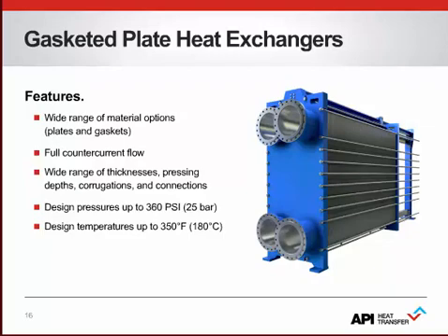Gaskets are typically made of rubber, such as nitrile or EPDM. Also, some fiber gaskets are available. The gasket is the biggest limitation in gasketed plate heat exchangers, both in terms of pressure and temperature.